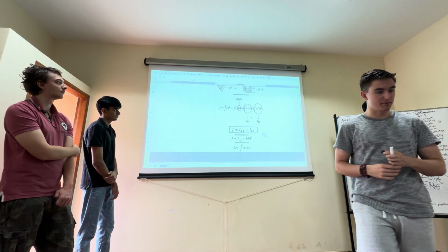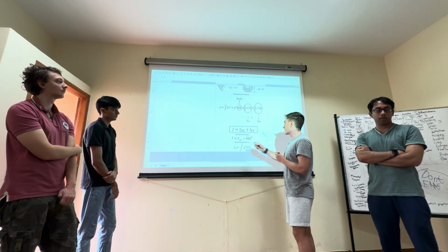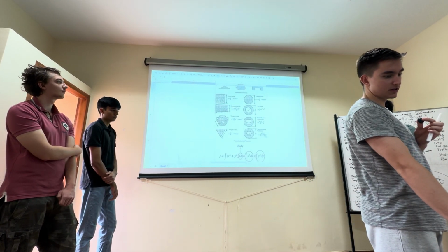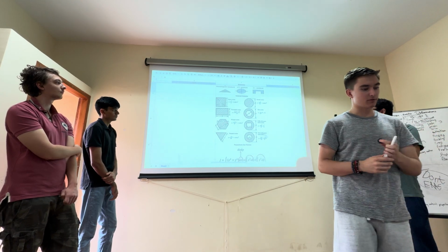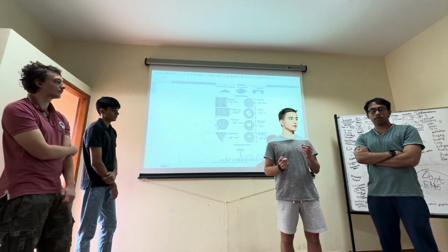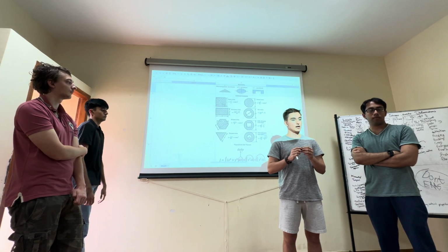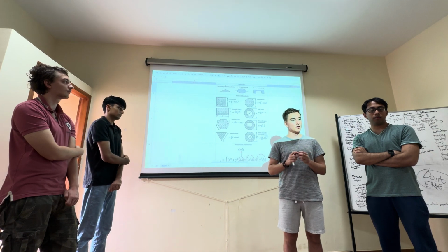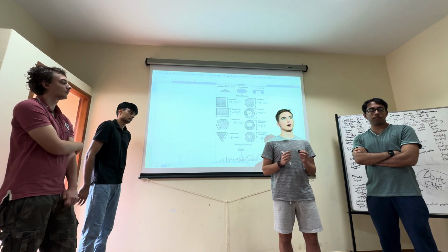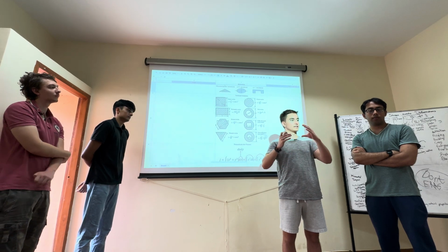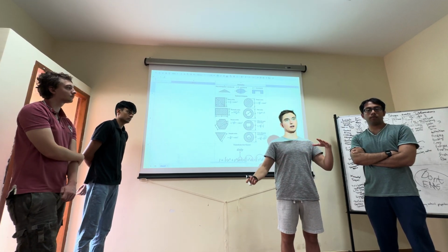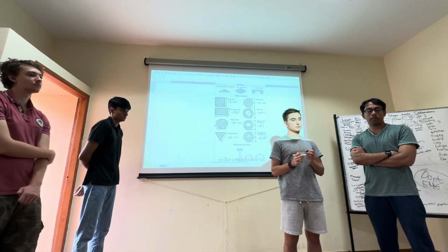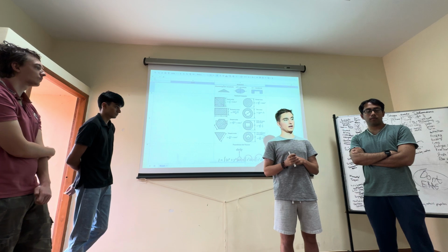When you use the perpendicular axis theorem and the parallel axis theorem, you can see that if we know, for example, up here, the moment of inertia of an object about its center, and we want to find it about a different point, then we can use those equations. That varies a lot based on whether you find it for a beam about its middle versus about its edge, basically where it's pinned, where it's supported. For example, we talked about in class wings that might be fixed at one point on the fuselage, versus wings where we have supports or struts that come up from the side. Those are going to have different types of supports, which of course affect how the moment acts on that wing.